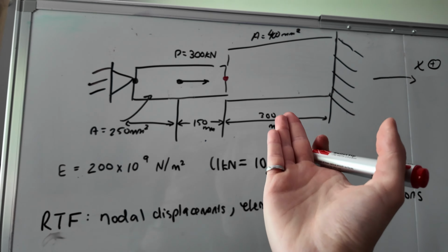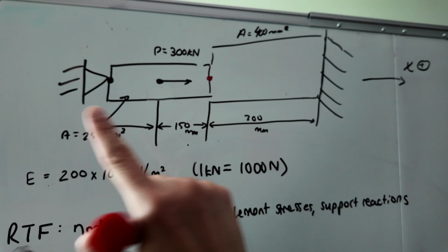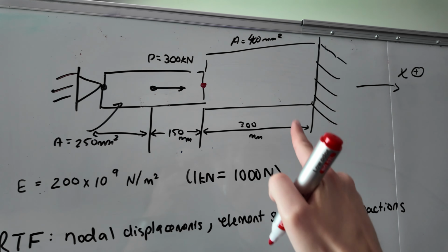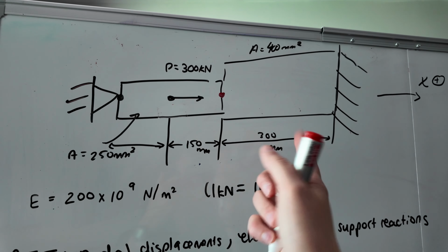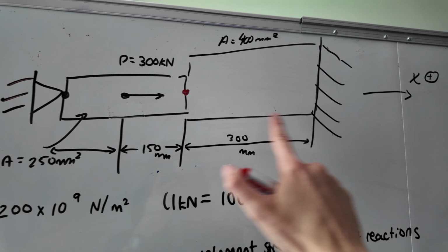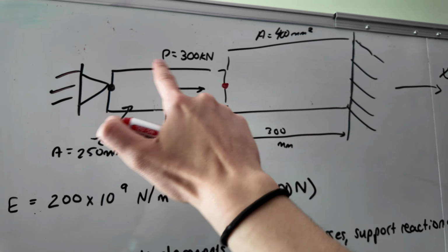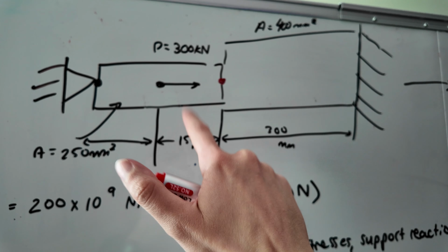After your givens are clear and you know what you need to find, the next step I like to do is to draw the nodes on my graph and label my elements. Now, intuitively, you might think that we only have 3 nodes, node 1, node 2, node 3, but where the force is applied here in the center of element 1 presents a challenge.